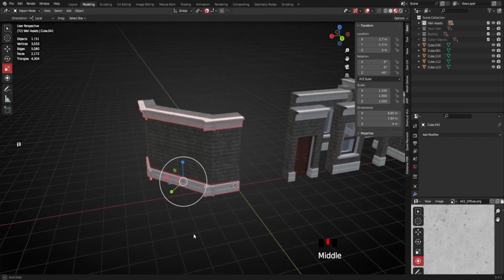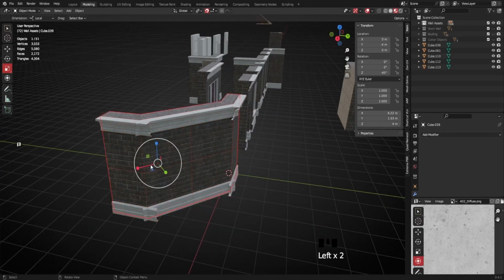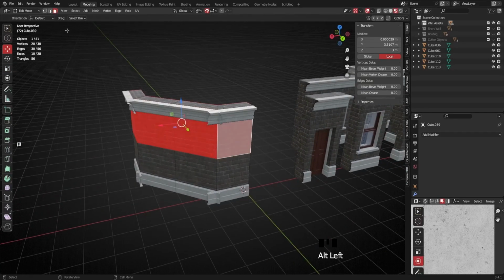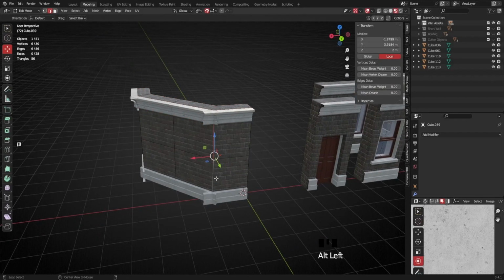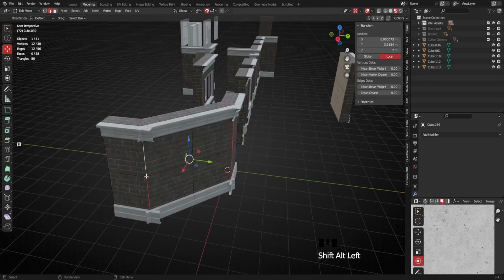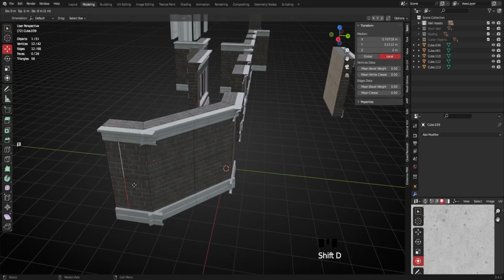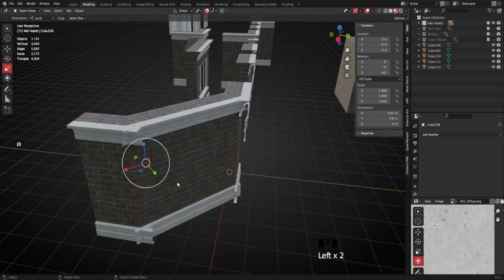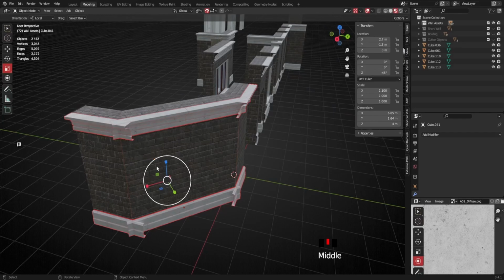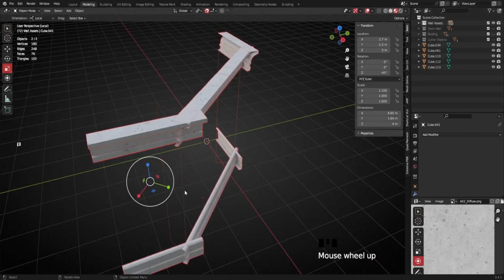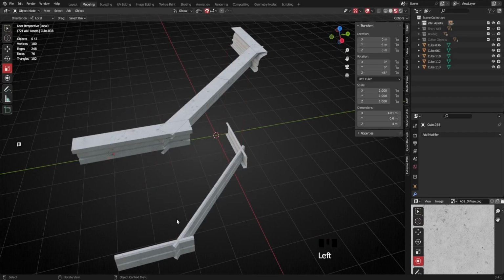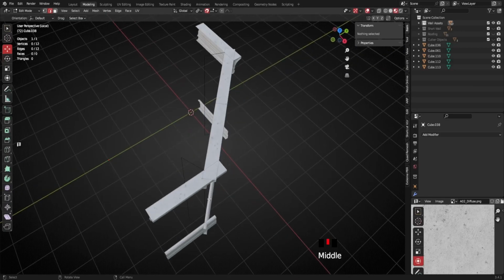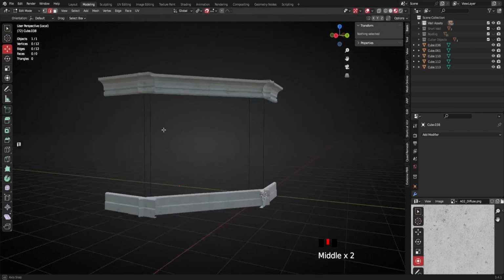So now we just need to cut these. And we'll cut these by doing the same thing we did with the wall. I'm basically just going to copy, go to edge select here. I'll just copy this ring of edges and this ring here. Shift D, E to separate. Now I'll just try to select those edges there and the crowning, and I'll isolate them. So the problem that we're facing here now is these aren't big enough. So they're not coming out past the piece of geometry that we need to cut.